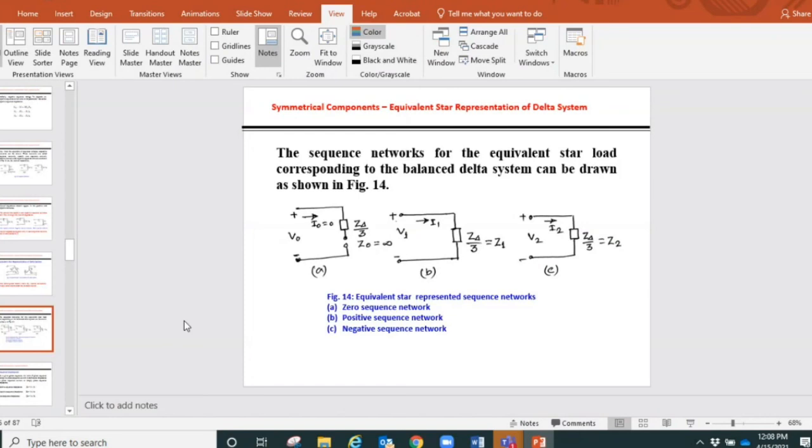The reactive power will increase. No, not that far. The reactance. Being simple, you have an inductance and you have increased the frequency from 50 to 60 hertz. The inductive reactance will increase. Yes, that's the first step. Because you have inductance. Inductance is what? It's L. And from L, what do you calculate in the immediate step?